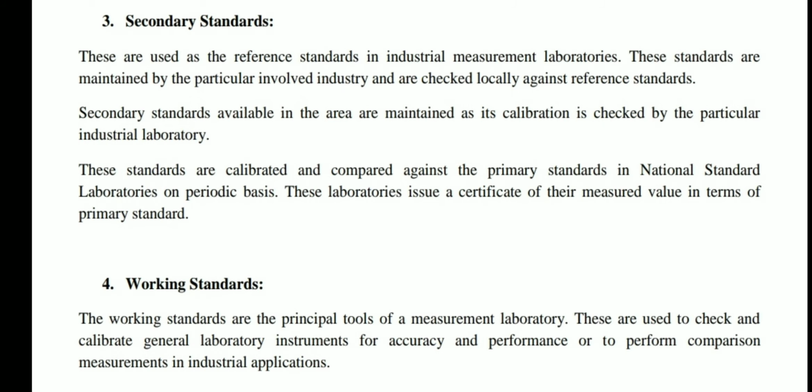Now coming to the third standard, that is the secondary standard. These standards are used as the reference standards in industrial measuring laboratories. These standards are maintained by the particular industry involved and are checked locally against reference standards. Secondary standards available in the area are maintained, and their calibration is checked by the particular industrial laboratory. These standards are calibrated and compared against the primary standards in national standard laboratories on a periodic basis. These laboratories issue a certificate of their measured value in terms of the primary standard.